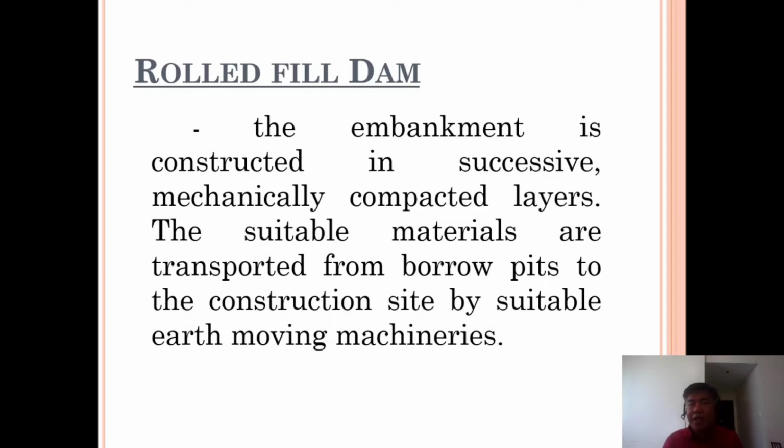But the problem is if the nearby materials have all been tested and fail the different analyses, then of course it becomes a different issue in terms of costing. So in the feasibility study, whether it will pass or not, the most important thing is that the materials pass the requirements, especially in terms of seepage and the exit gradient.